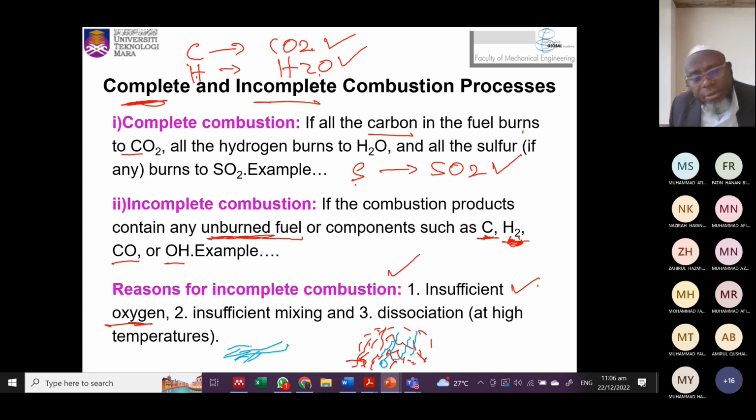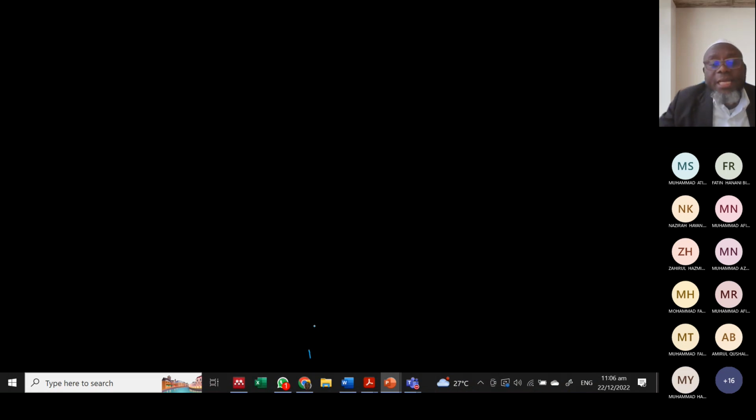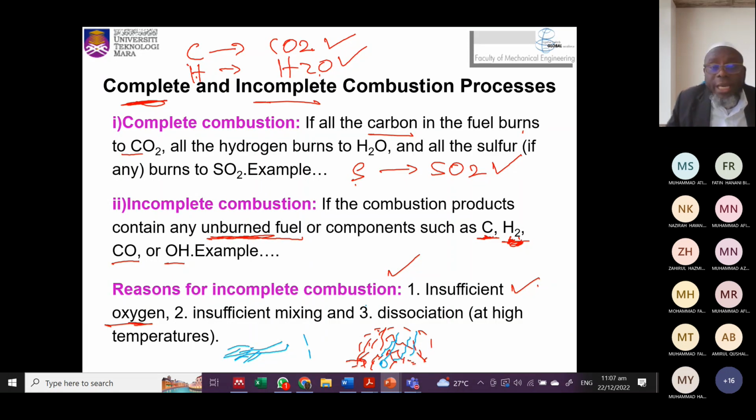You understand me? Sorry, it could be discharging some gases at the exhaust. Those gases, the color could be blue or light blue. These are the conditions. This condition is telling us that there is incomplete combustion inside the cylinder of the motorcycle. Okay, so it is incomplete combustion.